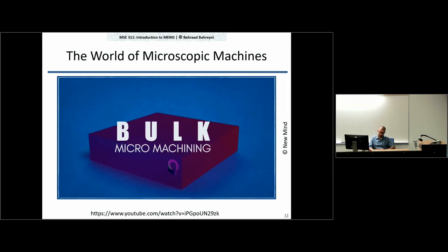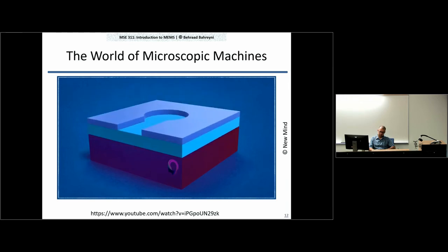In bulk micromachining, the substrate is removed in a manner similar to traditional integrated circuit techniques. An oxide mask is created and the exposed substrate is etched away. The pattern of etching is determined by the type of etchant. Isotropic etchants remove material equally in all directions, while anisotropic etchants are limited by the geometry of the structure to be etched. Anisotropic etchants usually etch faster in a preferred direction.